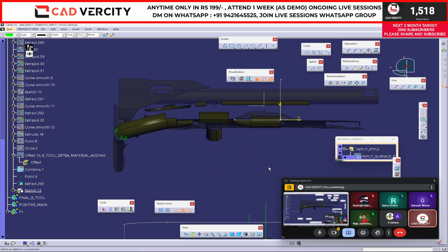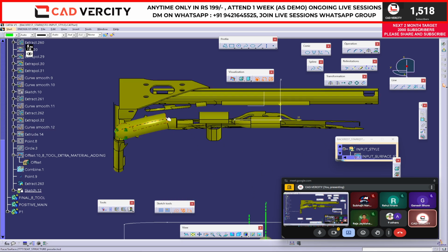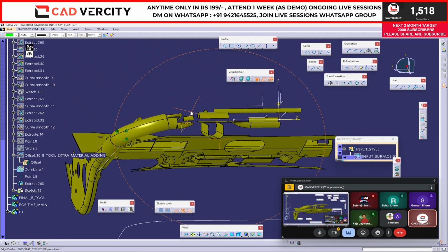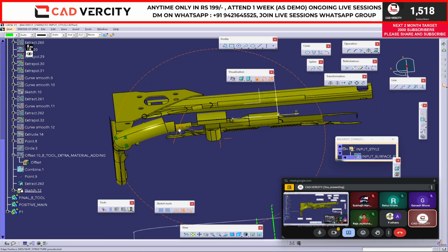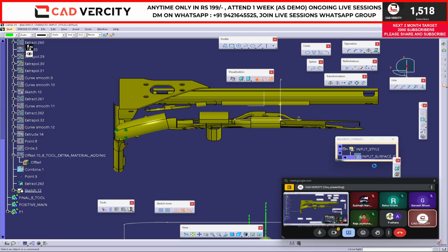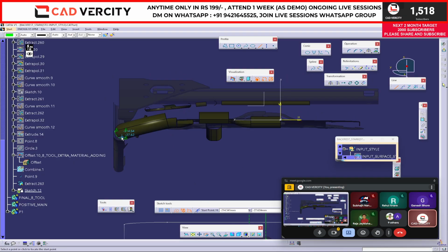Okay, again I will need a second. Normal, low light, line, right click. Concentricity, yes. Let's keep like this. Remove the construction. Draw a second line passing through the center like this. It should be horizontal. Trim.